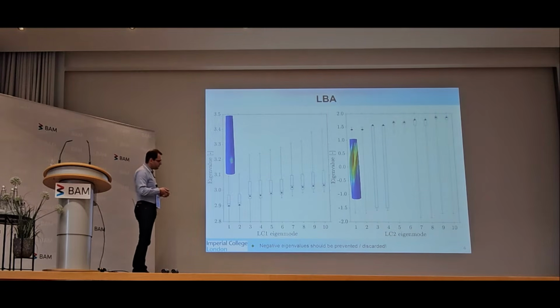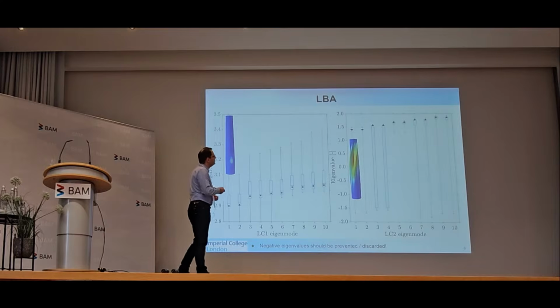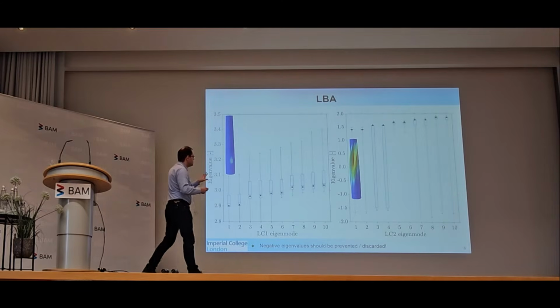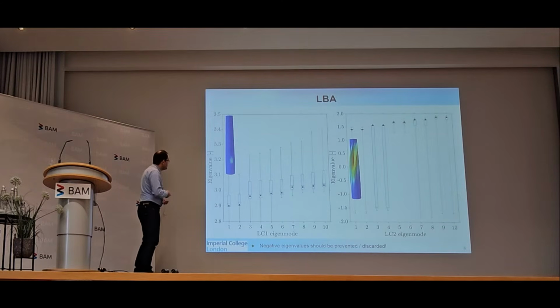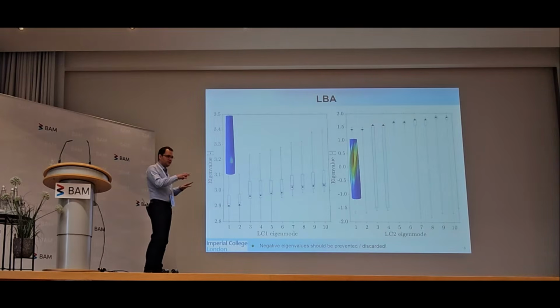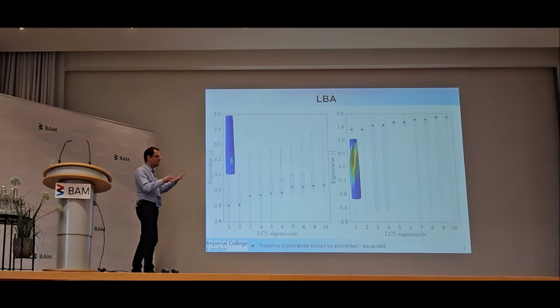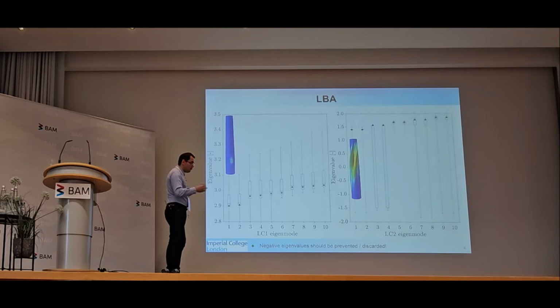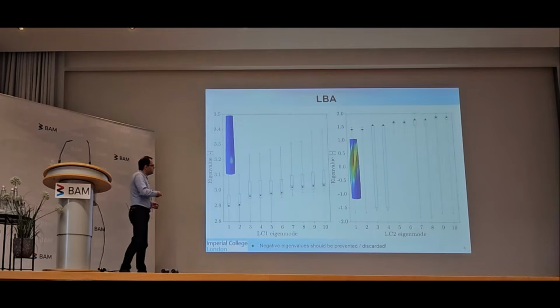Load case 2 has a torque on the top, and as far as the LBA is concerned, that dominates, and the critical mode there is a torque mode. So that's just to know what to expect. In terms of the spread of the results, these are the filtered submissions. So these would have been the submissions that passed the reactions check. They got this mostly right.